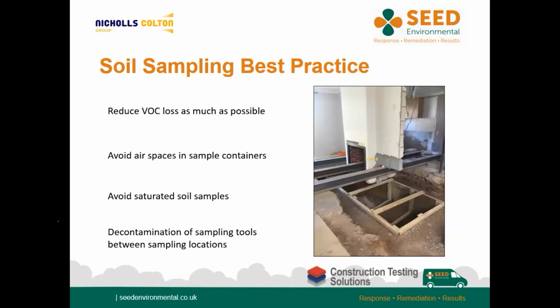Soil samples need to be retrieved by the laboratory in a condition that best represents the site conditions. Special precautions are therefore needed for samples suspected of having highly volatile contaminants, such as solvents or hydrocarbons. The British Standard BS 10176:2020 states two principal ways for taking samples for VOC analysis.